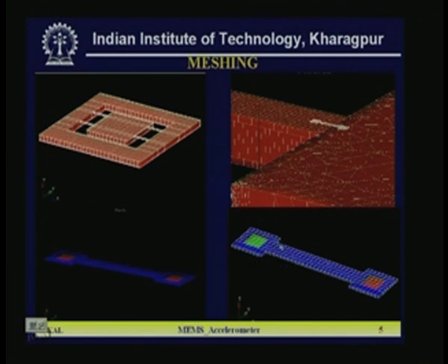The total resistance will be decided by the number of squares. If we know the width of this resistance and the total length of the resistance, we know how many squares there are, and that multiplied by the sheet resistance gives the total resistance. Now the two ends of the resistance have two bonding pads, contacts. These two colors are the two contact regions, and if you metallize it, the contact must be at the middle of the resistance. So for alignment tolerance we have allowed 10 micron on each side. If the width of the resistance is 20 micron, the edges will be 40 by 40 micrometer.